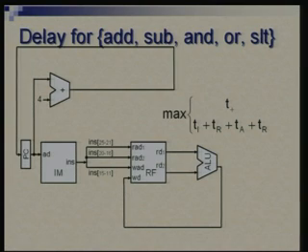These get cascaded, so all these get summed. The other path is going through the adder to compute PC plus 4. Now if all are comparable, then the first one is actually meaningless; I could straight away neglect that, and the second expression would dominate. But let me be a little open here and say that the clock period is the max of these two.